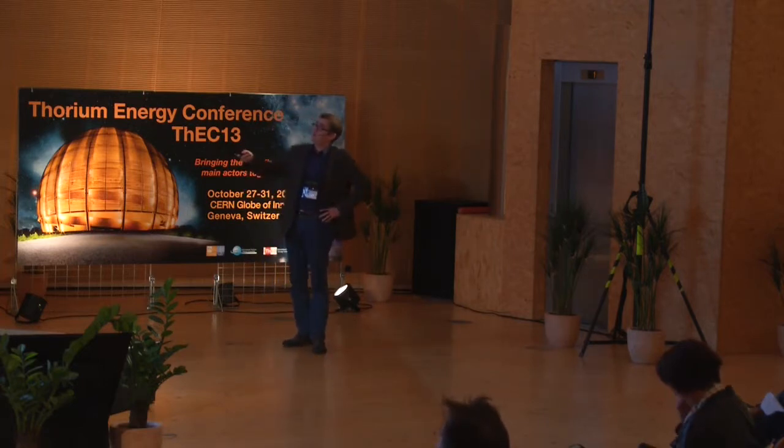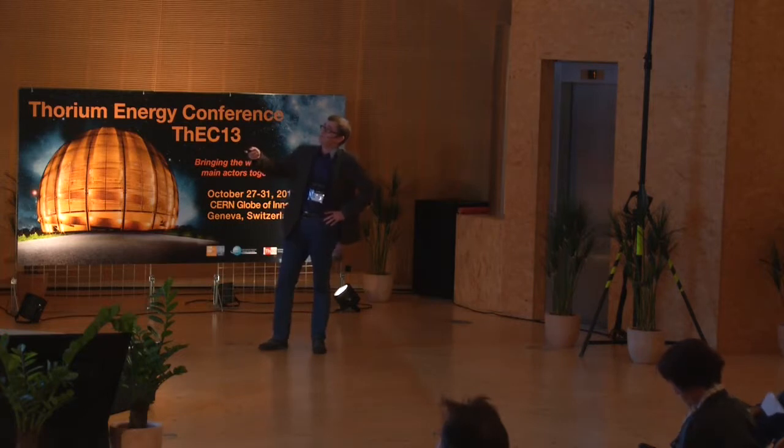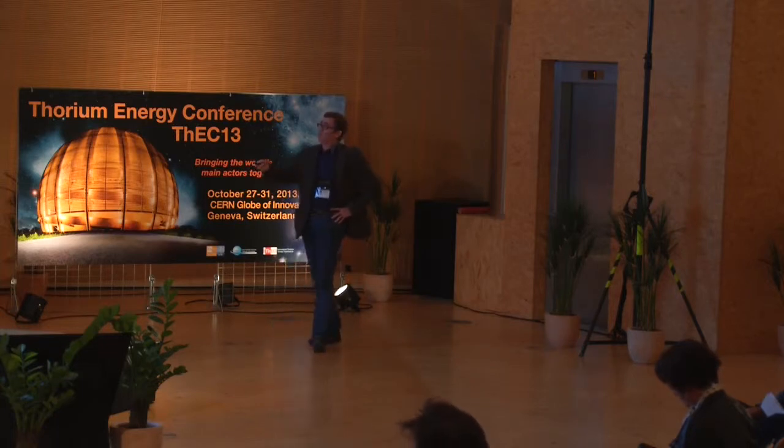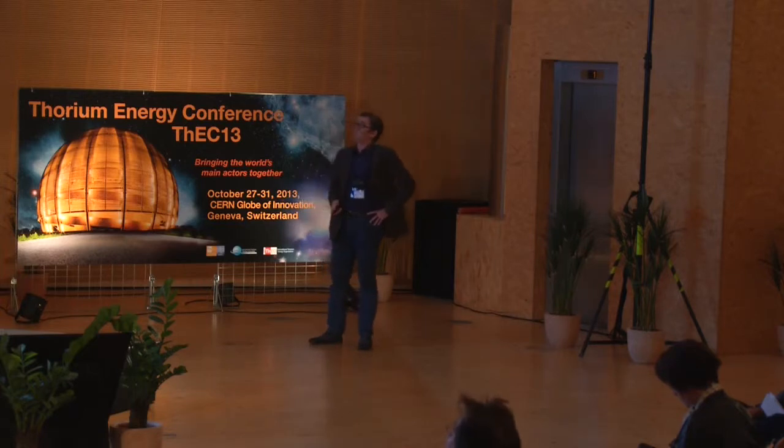a concept design of a 3,600 megawatt thermal reactor, a fast reactor cooled by sodium, fueled by mixed uranium-plutonium oxide and stainless steel cladding. And I put here the main parameters.